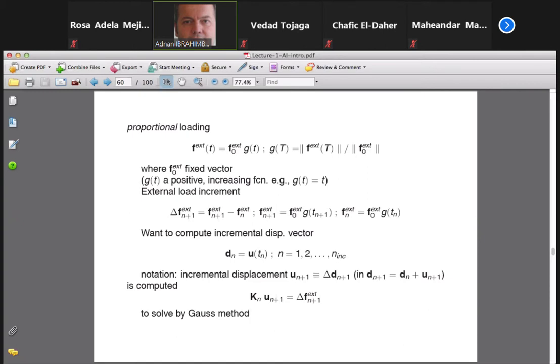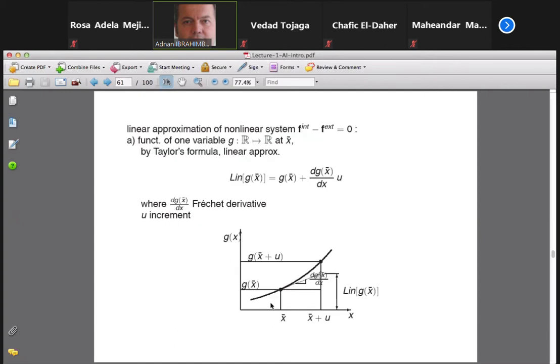So the main idea of how to get this tangent stiffness is obtained by so-called consistent linearization. What that means is basically if you look into what the Taylor formula applies for any function g of x, with respect to x, it goes as follows. Imagine this is your nonlinear function. It could represent a particular nonlinear response of my, let's say, truss bar when I have only a single degree of freedom. So when the displacement increases, I have a nonlinear response, but I want to approximate this with a particular linear response. So I simply take the Taylor formula and I truncate after the second term.